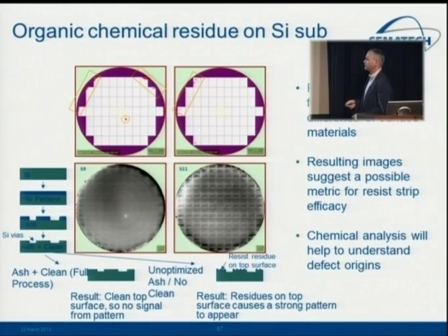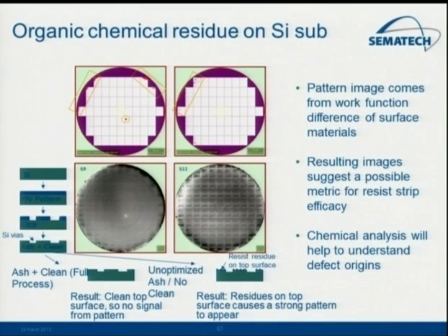It can also be very sensitive to changes in surface roughness or residues left on the surface. And here's a particular example of one of these maps, and this is even using a little bit of a patterned wafer. You're not trying to image the wafer and find the defects, you're just looking at this scattering map. And what you can see is that this particular step was leaving a residue of the photoresist on the wafer. With that scattering map on an unpatterned wafer or a patterned wafer, it can be fairly quick to identify what can be very small variations with regards to residues on the surface.